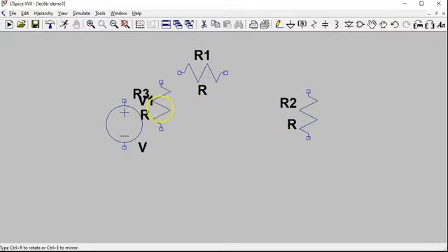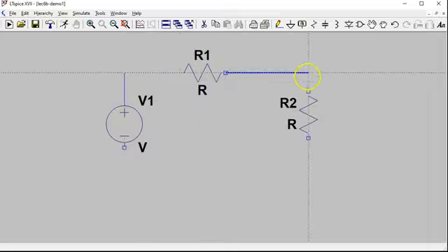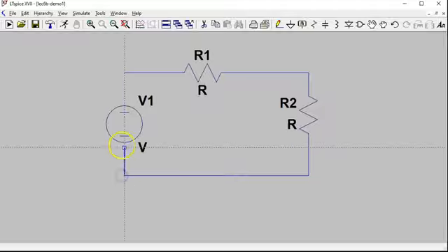In this location, I'm going to press escape, go on here and click wire. That's going to allow me to draw wires. I'm going to connect these nodes, and once you click from one terminal to the other, it's going to terminate the wire. So you create a new one from this terminal to here, then another one from here to here, and there.